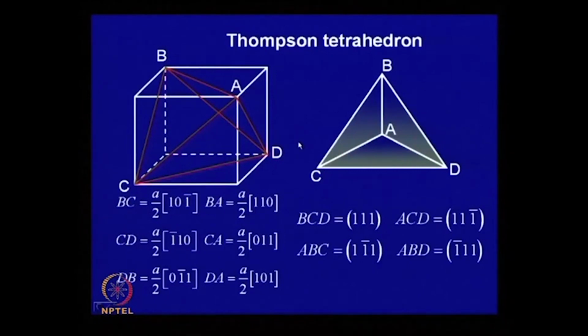We also looked at the interaction when a dislocation moving on a particular plane intersects dislocations which are perpendicular to the plane, and in that case what we have is an interaction with a forest dislocation. In that case it forms jogs or steps in the dislocation line.